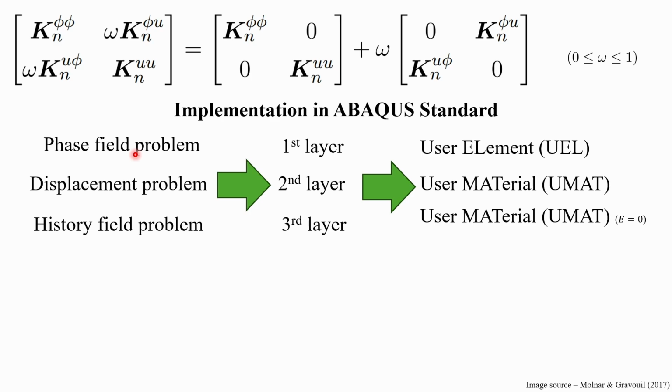Standard elements in Abaqus are like plane stress elements, plane strain elements, dynamic explicit elements, thermodynamic elements, and so on and so forth. But this phase field element is not a standard element in Abaqus. So you have to define or create your own custom element, and you do that using a subroutine called the user element subroutine, or UEL. It is a very involved process.